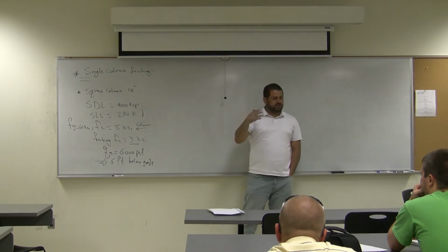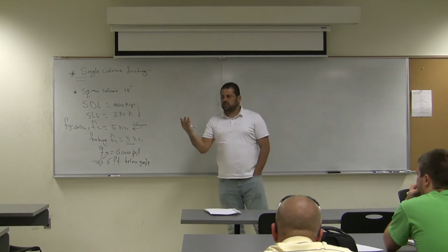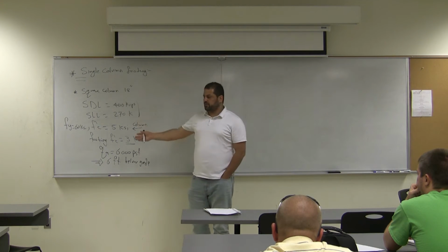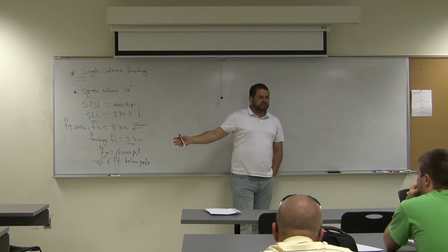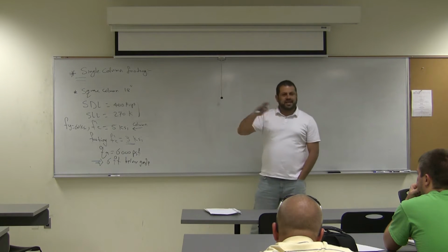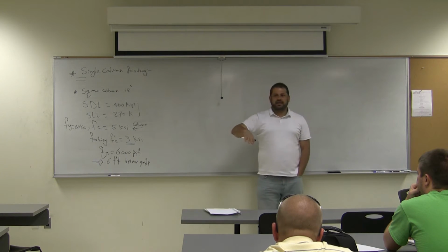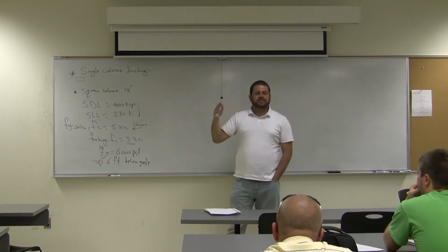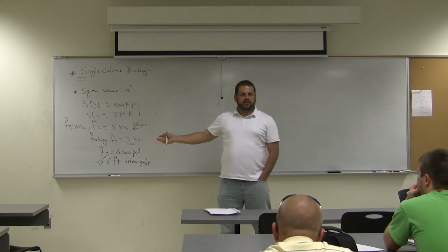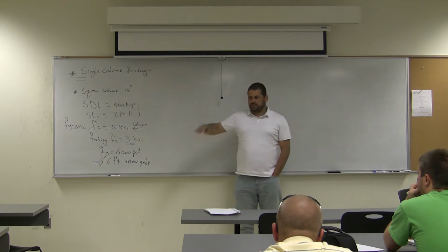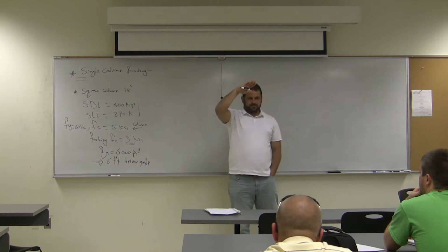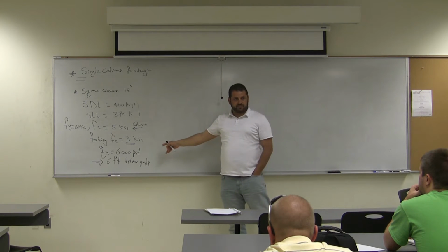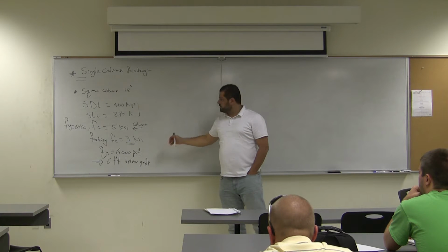You can assume the unit weight of the soil is 100 to 110 PCF. We know the concrete is 150 PCF. As I told you, take an assumption of that area and mix an average weight between concrete and soil. So you can take 125 PCF, pounds per cubic foot, as the weight of the material on top of the footing, to calculate the effective bearing capacity as follows.